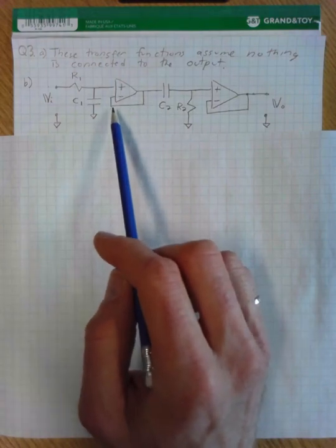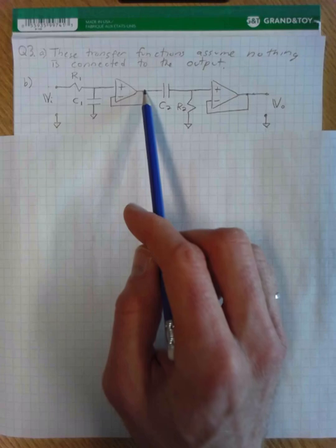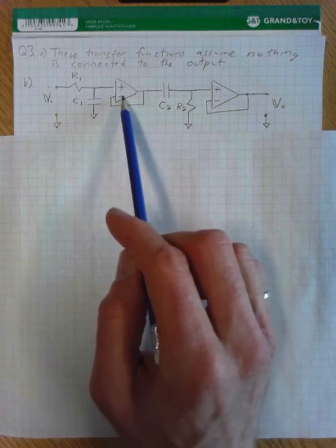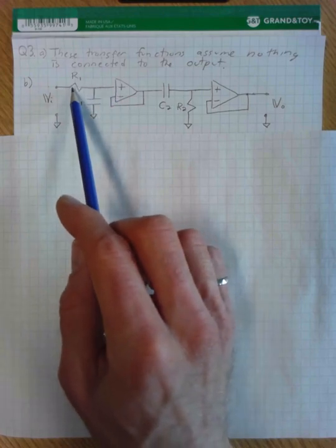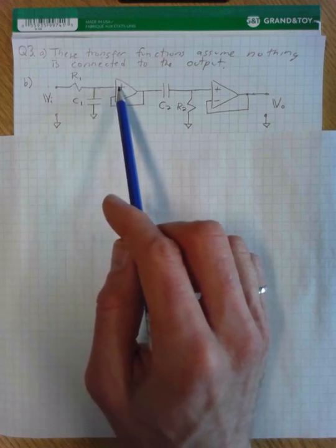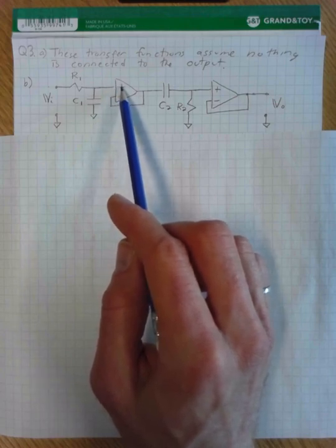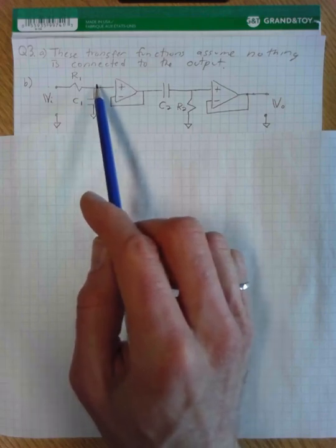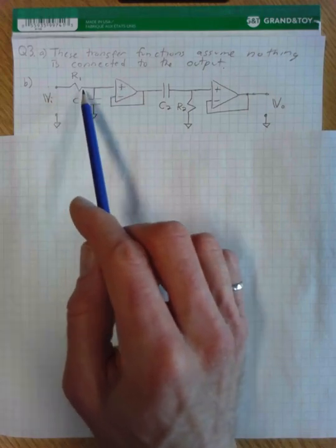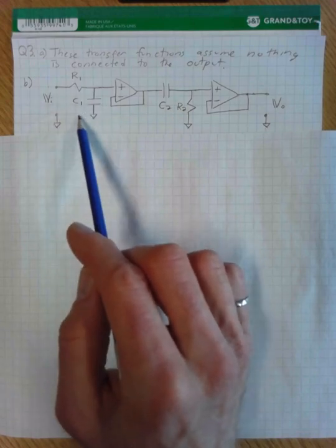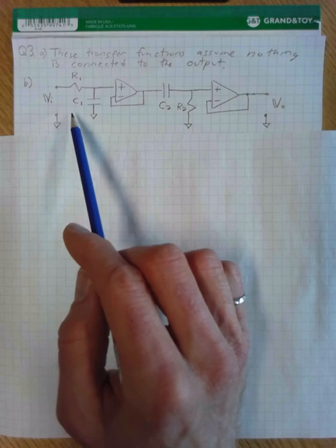And the reason why this works is because, first of all, when you connect the output of the op-amp directly to the negative terminal, you get a non-inverting amplifier with a gain of 1. And when we connect the output of the low-pass filter into the op-amp terminal, because the input to the op-amp has such a high resistance, essentially no current will flow here, and all the current will flow down through this loop through the capacitor to ground, and that's what our original derivation of our transfer function assumed.